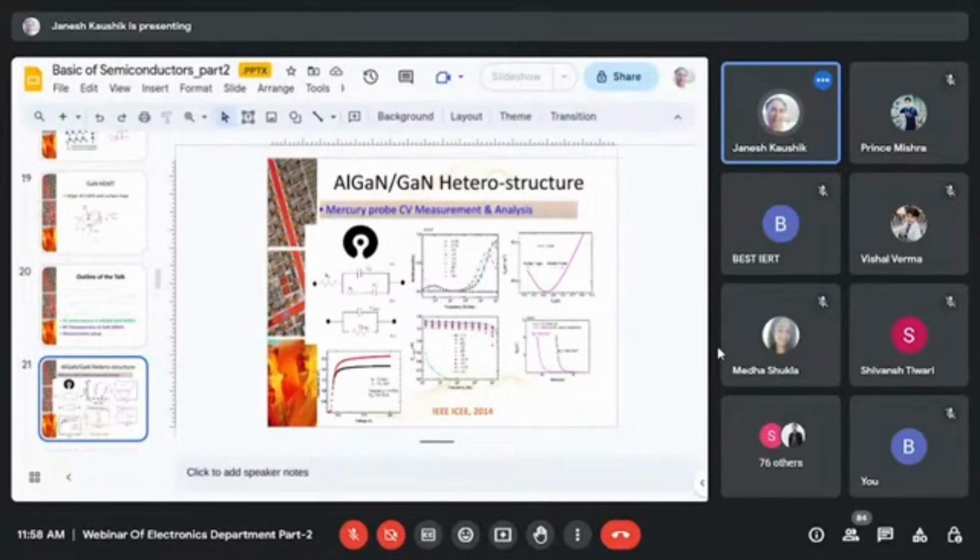When we are measuring a capacitance, it's not a simple capacitance; it's always a combination of conductance G plus j omega C. So we have to first remove the DC conductance and calculate only the AC conductance, and that G by omega has the same unit as capacitance, and we compare it with the C. If it is much more than the C, then the capacitance value can't be used for the analysis, but G by omega values can still be used to calculate the traps, and we can calculate the energy distribution as well as the density of the traps present, and how they behave with the frequency.